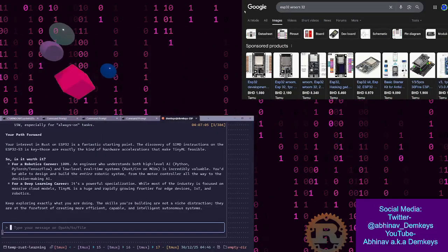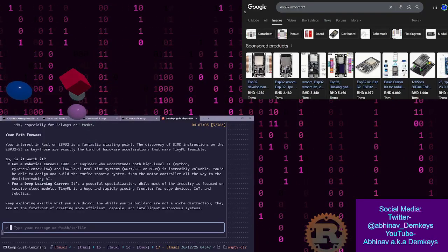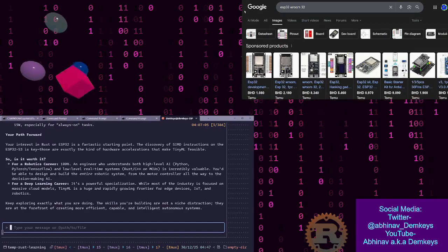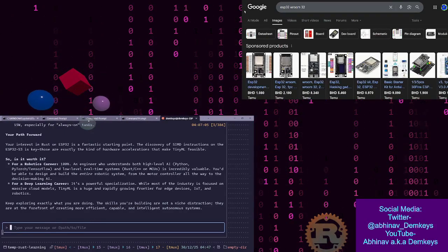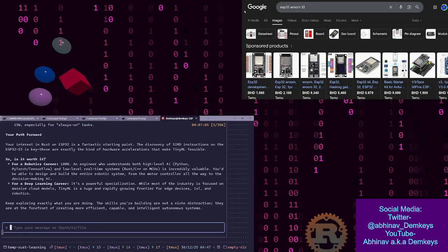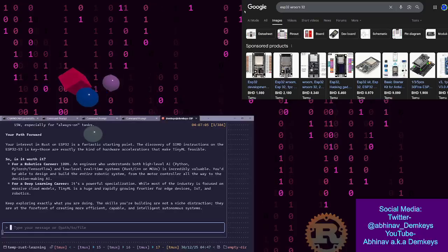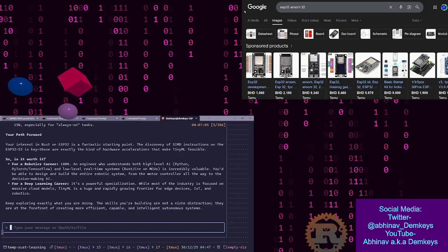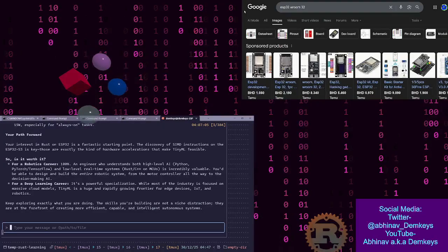Okay, software cooling. You can lower the clock speed. You can use deep sleep and modem sleep. In Rust, you can tell the Wi-Fi radio to go to sleep between beacons, and this is the number one way to reduce the heat while staying connected. Which board are you currently coding for?